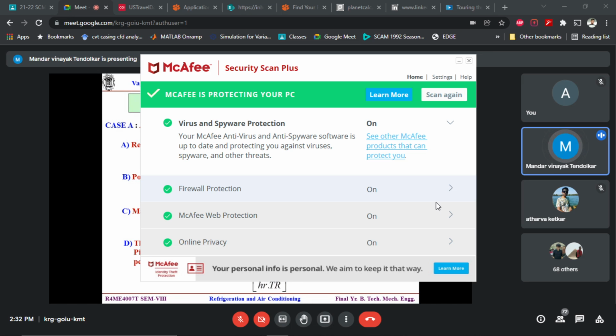And that is corresponding to 1 TR. So this is per TR. Correct? Then theoretical piston displacement, that is m dot into V. Your m dot itself is per TR, so multiply by the specific volume. You get the volume flow rate also per TR. Correct? One ton of refrigeration corresponds to 211 kJ per minute.